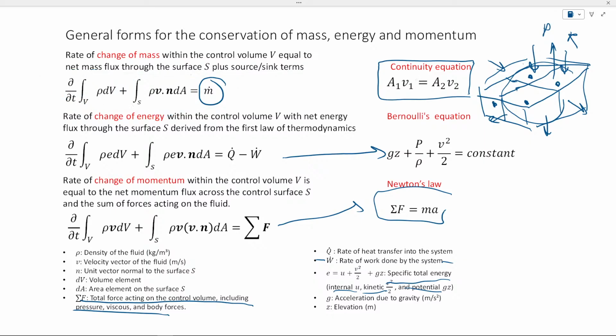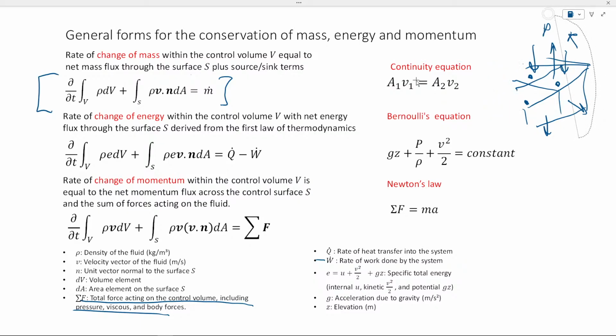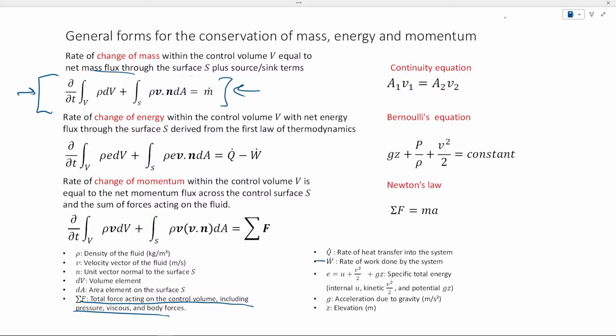That is the general equation that we would be using when our modeling application is based on the conservation of mass. Most modeling applications that I have done are based on the conservation of mass, based on this equation. For example, groundwater flow is based on this. I have a change in head inside my model, some changes at the boundary of my model, and then some source and sink terms. Contaminant transport is based on the same equation. So I can derive the groundwater flow equation from this, and I can derive the contaminant transport equation from this.